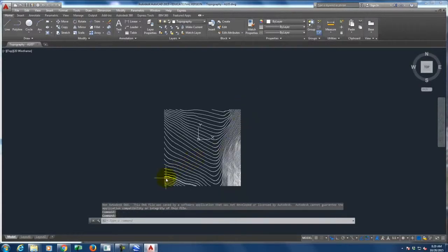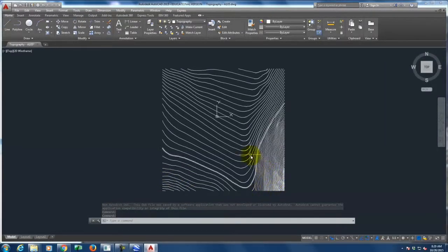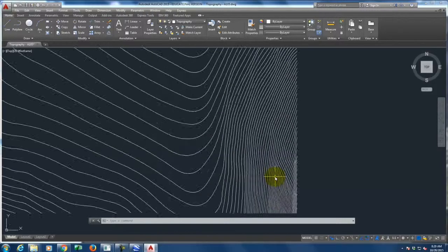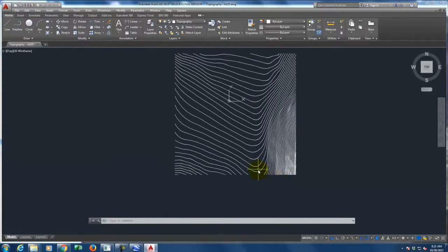All right, so AutoCAD's loaded. So this is a set of contours that represent your building site. They're 1 foot intervals, so every 1 foot going up the site. So it's not a particularly steep site until you get over to this side, which is obviously quite steep. This swale right here is where the Merced River flows through, on your site. A lot of you will probably build in this relatively flat area here.